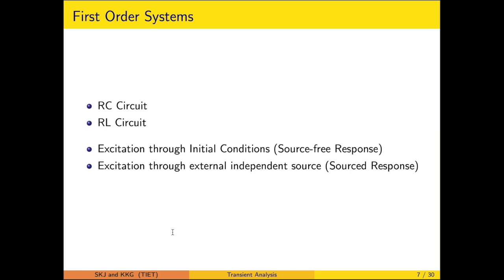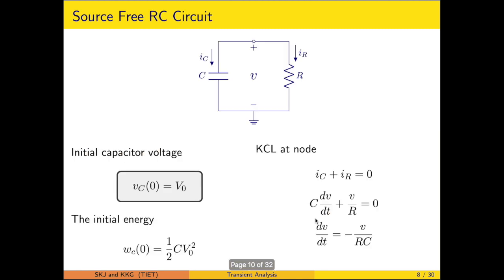As mentioned, we are going to analyze the first order system, so RC or RL circuits are considered. Now we will be analyzing the source free response. Source free means the response is initiated because of only the initial conditions.